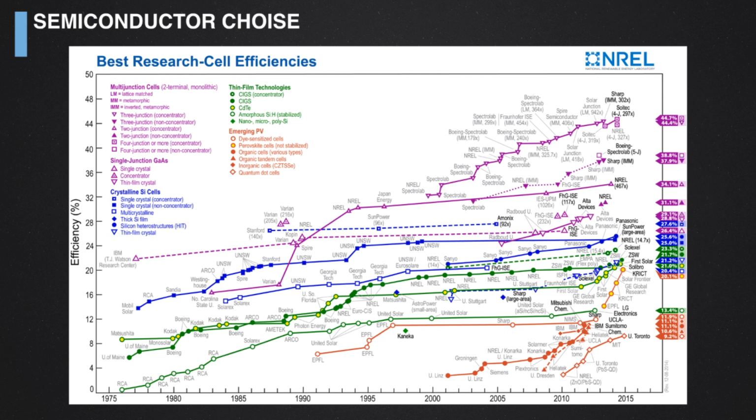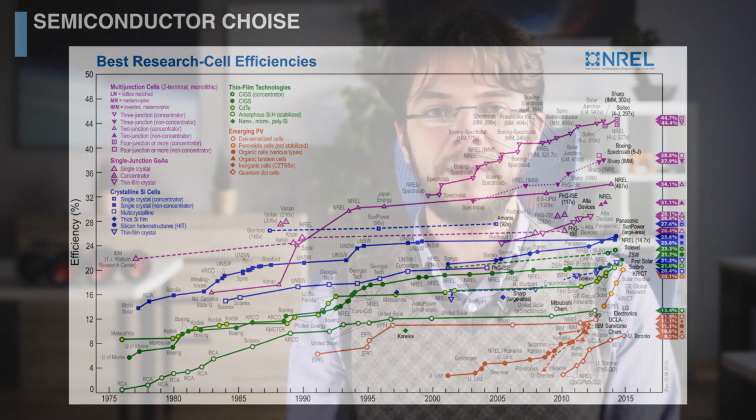Or more recently, the so-called dye-sensitized solar cells were developed, where the concept is radically different. You have titanium dioxide in a nanostructured form that is used to separate the excitonic couple. There is a dye, a molecule, which is converting directly the energy associated to the electromagnetic wave into the hole and the electron, and you have a layered structure, which is also, by the way, transparent, so it gives you new means of using the solar panels in windows, for example.